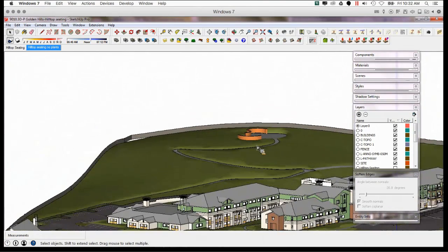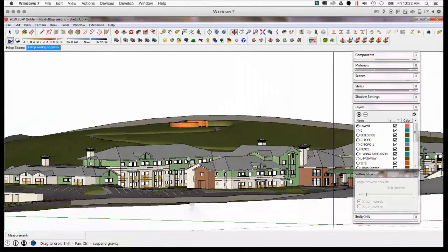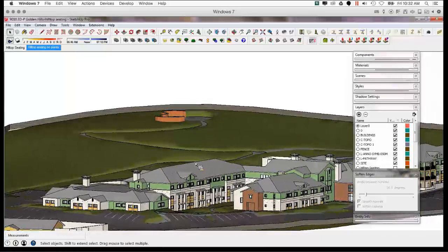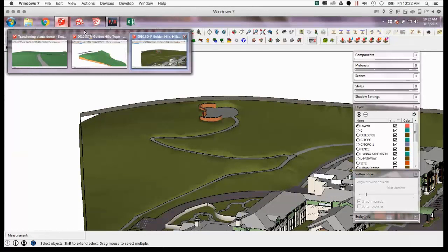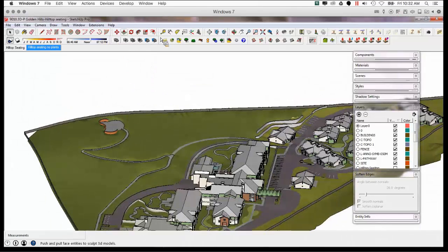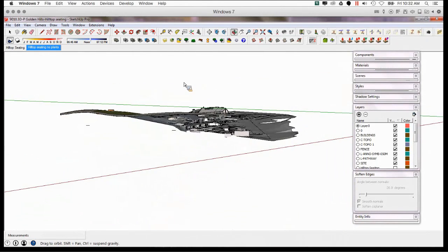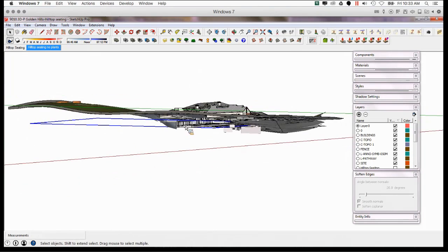So how do I actually get those elevations now set so that we can bring them over into CAD? You remember that we did that one export of the line that we had for that section cut, and you're going to see here, it's not in this model. Let's go back over to, that's fine, we can import it in here really quick. So I'm just going to import that symbol line, and what you'll see is that line work that came in right here, and I can select all on that same layer, which is a nice little feature, and I can go ahead and group it so that it's at least all locked in, and now I can move it above if I want to,